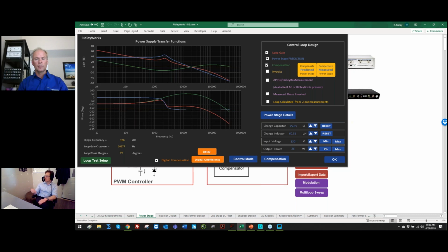You could do loop gain sweeps in Psim with different loops working at different execution rates, so that proper Z-domain discretization is possible, where that signal path only executes at that interrupt rate. And you can do S to Z conversions with bilinear or backwards Euler. There's a conversion tool to convert whichever control system you want, so that you have Z-domain ready code or a controller, and then the whole implementation path down to the control system that you implement.